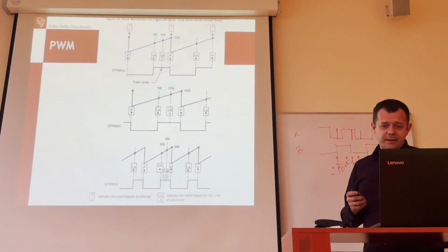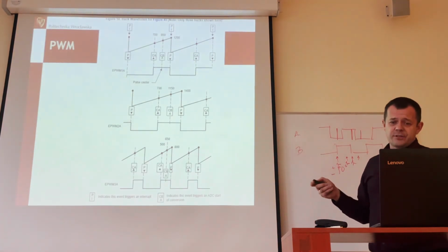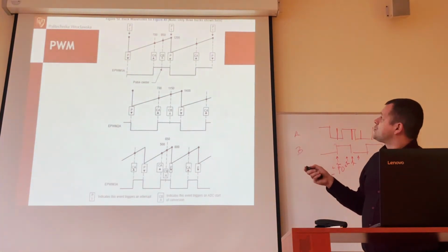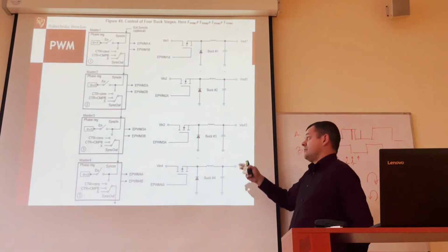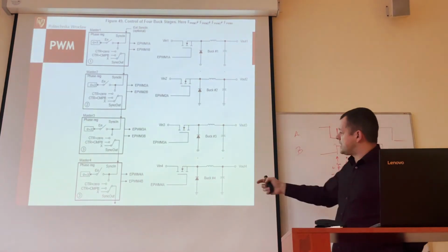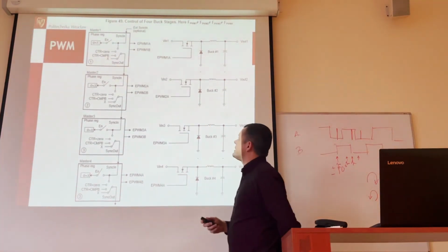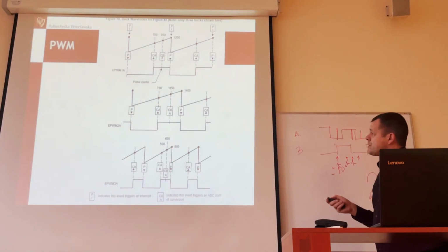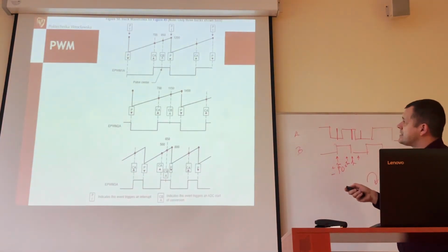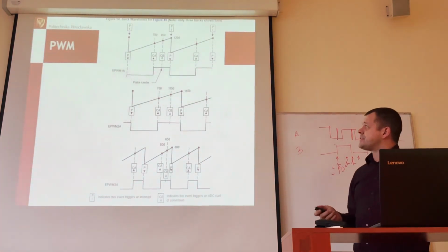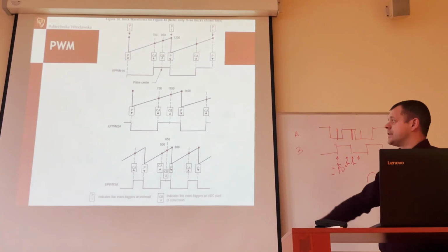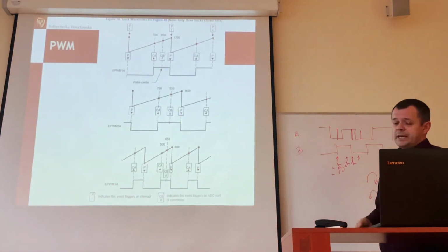What is happening then? If there is no synchronization, switching happens at random times, because each DC-DC converter in this example works differently, which means that current switching occurs at various times, which of course means that we've got various spikes, current spikes or electromagnetic interferences occurring constantly, at random times.